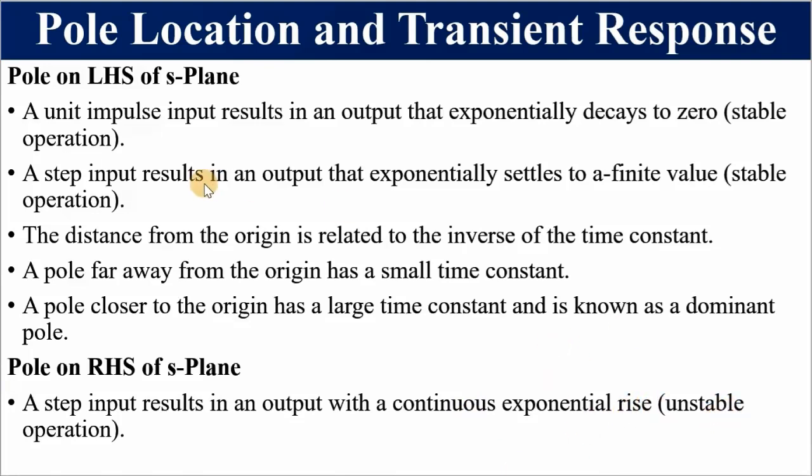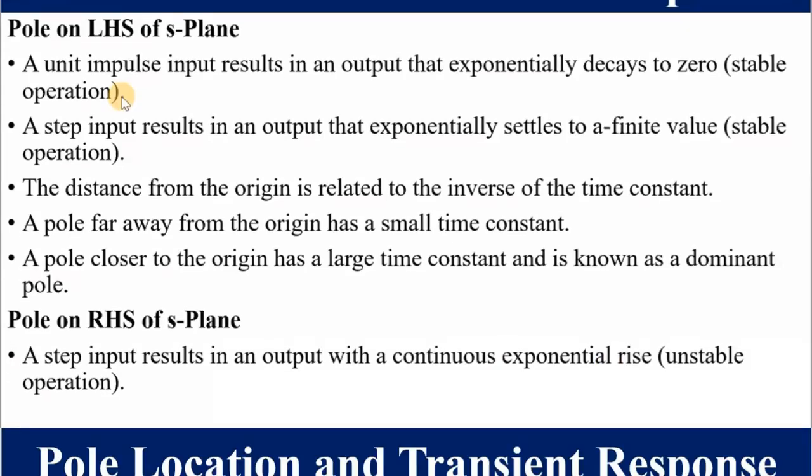So guys, take note, in a control system, for stable operation, the pole location must be on the left hand side of the plane. Otherwise, if it is on the right hand side, we will approach instability. And when this occurs, what are we saying? We have reached an unstable operation, whereby we have an oscillating control system, or whereby there is a continual increase in the output, which results in the catastrophic failure of the system.